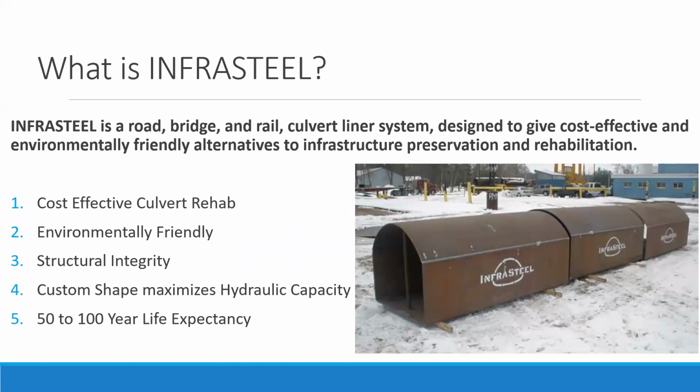So InfraSteel has a calculated design life based on the thickness of the liner chosen for each project. Once the load-bearing thickness is determined, steel is added to the thickness for each year of design life required, taking into consideration the added copper in InfraSteel for corrosion prevention. This copper content negates the need for any additional coating to the InfraSteel pipe.